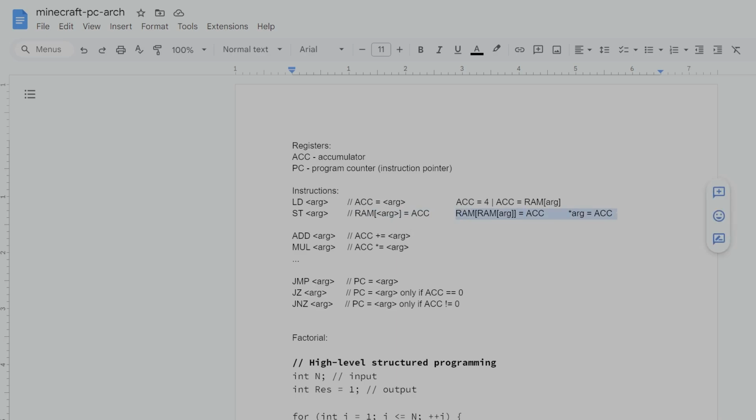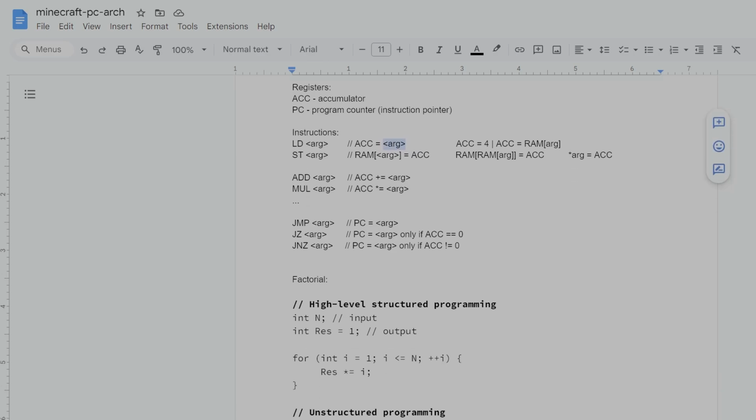This is like prototyping some other indirect stores that I don't think I implemented, but I basically implemented the simplest possible primitive opcodes that I could. I also distinguished between direct and indirect instructions. Direct instructions treat the arg as the literal value, and indirect ones treat it as the address to read from memory. So I have one bit in the opcode that selects between those two modes.